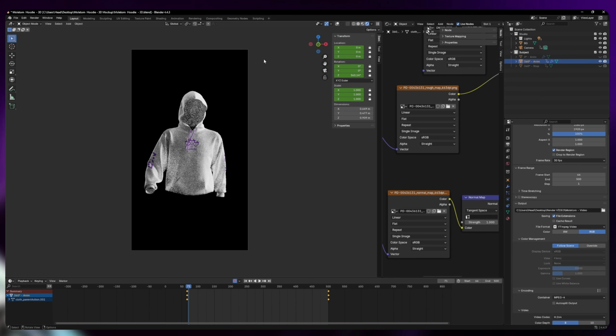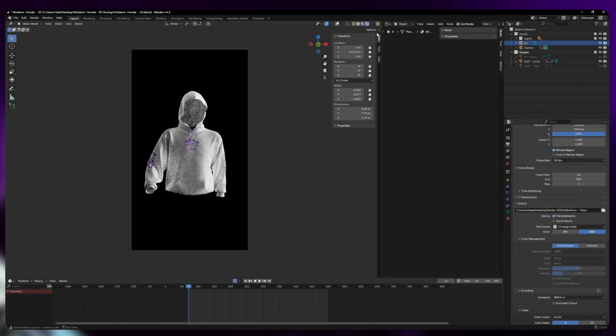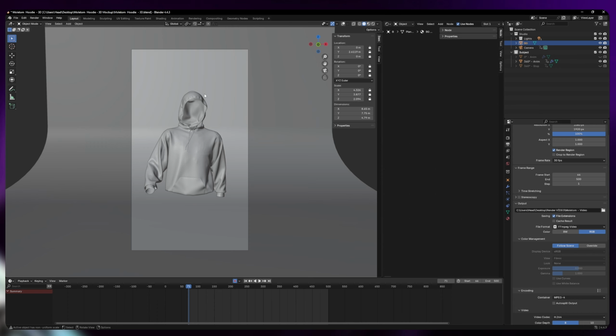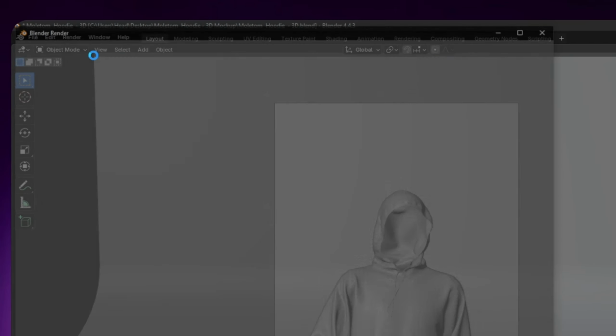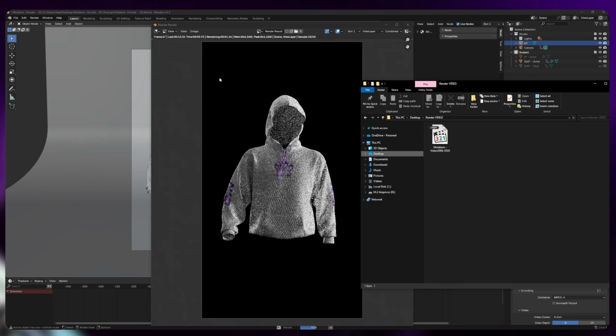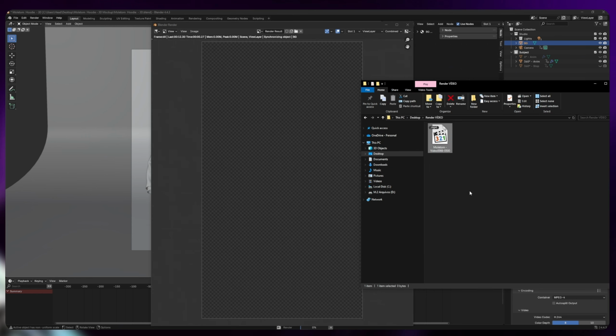Now we will put it to render, which is the process of actually creating the video. It's going to take this 3D that's here on our screen, animate it and make the video. And the first thing I tell you to make this process lighter is to put it in this mode again without the texture. For now, leave it without the texture so it won't stay in the preview here. Beauty, you come up here now in Render, click here on Render Animation and you're done. Here it will start rendering, turn this really into a video, and it will be saved in this folder.